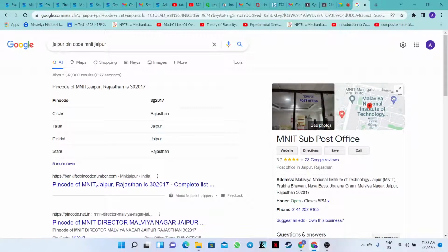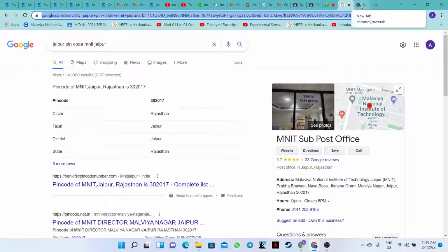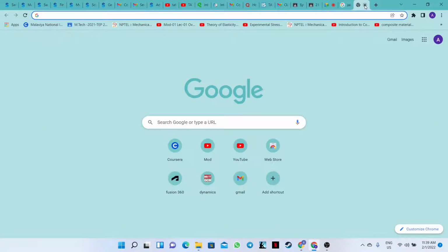Right? Orientation is given by a motion of pure rotation. This link is under pure rotation because translation is not here. Each point moves on concentric circles, correct? So it is in pure rotation. And the point which we define as a reference point on the link, that is the pivot point. So that way we find the position of the crank.